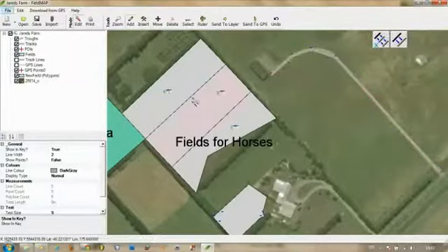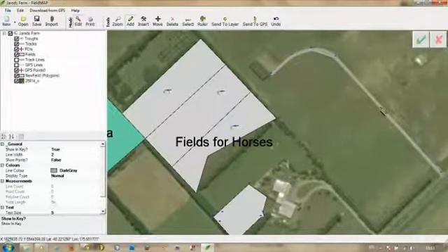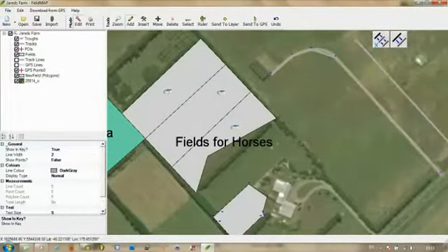To draw a parallel line with the polyline tool, ensure you have the polyline layer selected and that you are in edit mode, and then click on the Add tool. You should see two buttons appear on your map, the Freeform Parallel Line button and the Fixed Interval Multiple Parallel Line button. Freeform parallel lines allow you to click on a line and drag a parallel line out in place by clicking on the mouse. This is good if you want to snap the parallel line to an existing point but don't know the exact distance that will end up being between the two parallel lines.